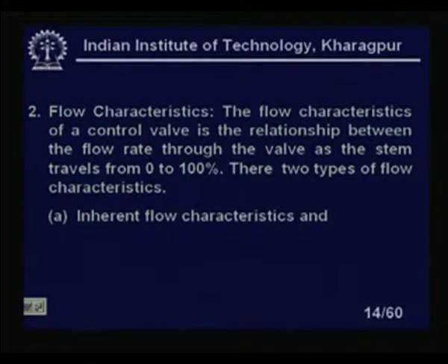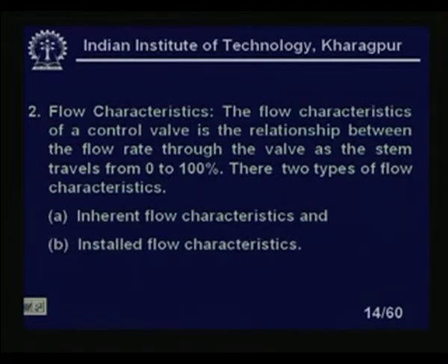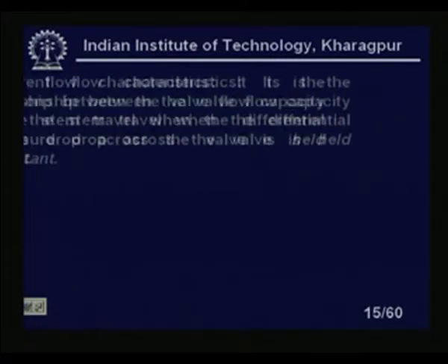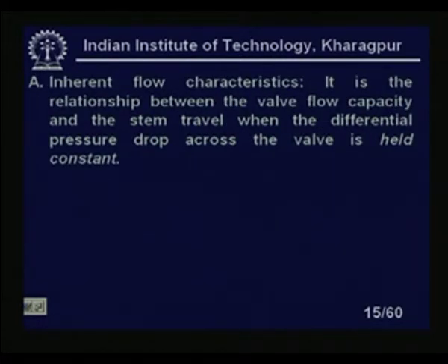Now, there are two types of flow characteristics. One is the inherent flow characteristics, and the other is the installed flow characteristics. We will study these in detail. Inherent flow characteristics is the relationship between the valve flow capacity and the stem travel. As I told you repeatedly, the stem travel is basically the percentage lift of the stem. This is when the differential pressure drop across the valve is held constant.